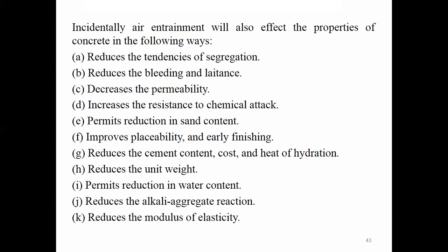Abrasion resistance and all, we will be discussing in the pavement structures. We all know what is meant by abrasion. Abrasion is the wear and tear effect of the surface. It may be any surface, but here we are discussing concrete. Wear and tear shows the durability nature. In a pavement, so many vehicles are moving and crossing. It will cause some wear and tear effect on the concrete surface, the pavement surface, and that is called abrasion. So the surface should be abrasion resistant, then only it will withstand over time. The durability of the pavement will not get affected.